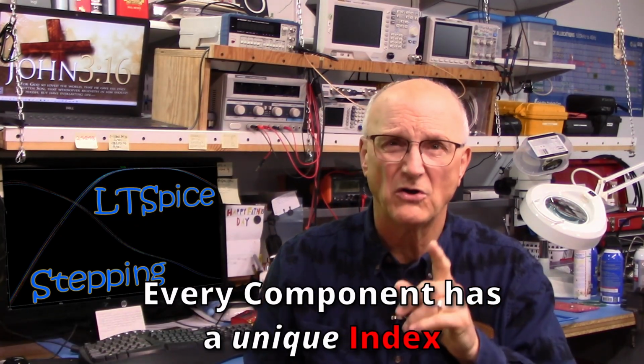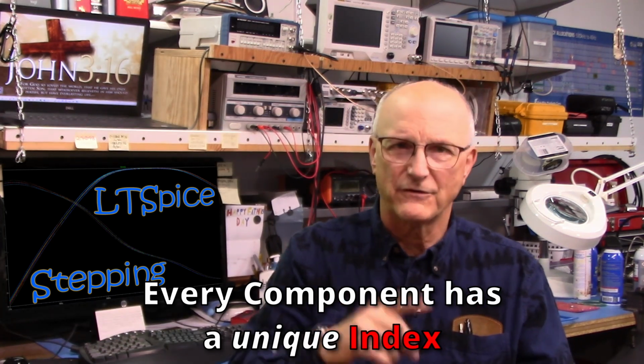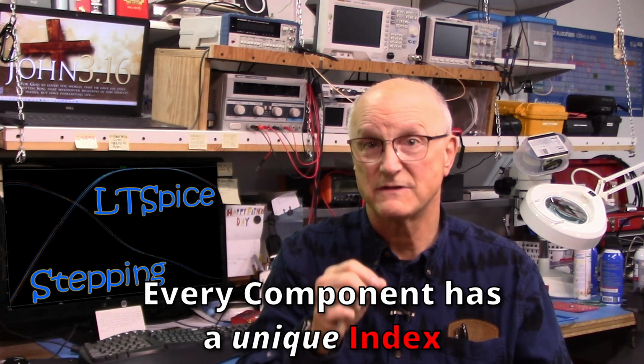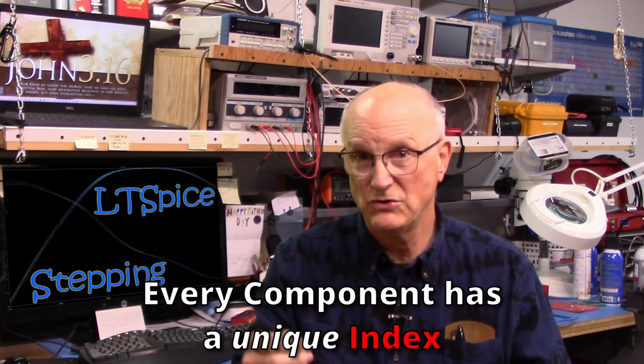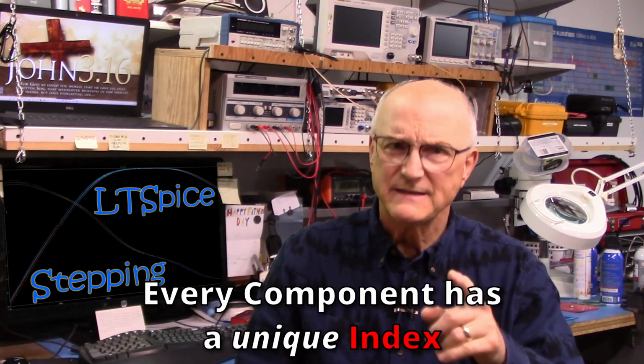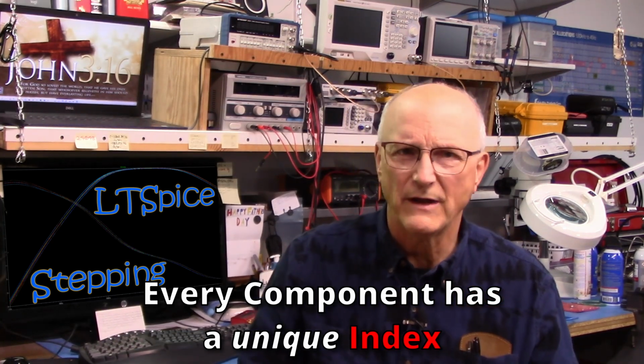Now, with all of the PSpice directives put in place, we need to assign values to our components. Every component has what is called an index value for this process. The first component has the index value of 0, the next is 1, the next is 2, and so on. This is important to remember as we enter the value for each component.